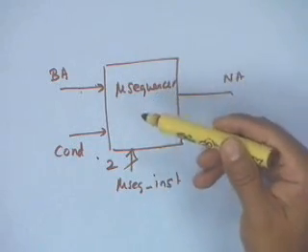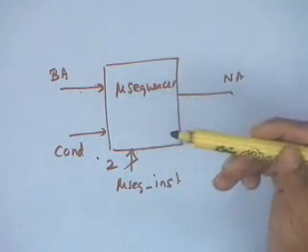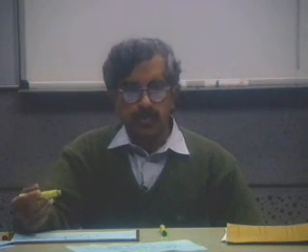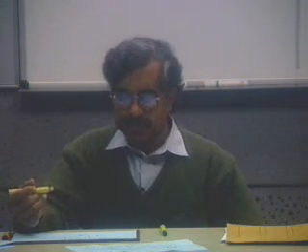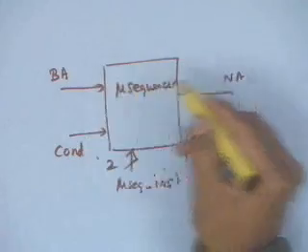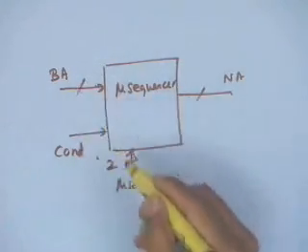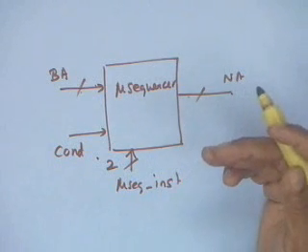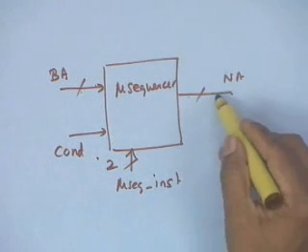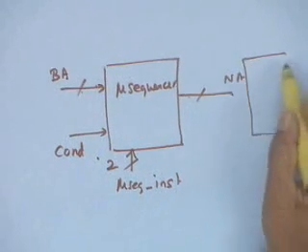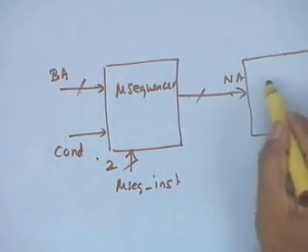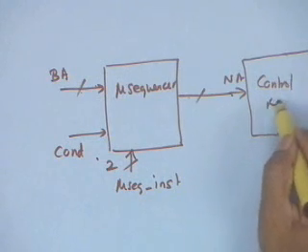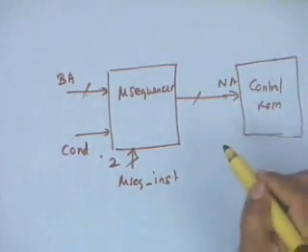The way the microsequencer is designed is you can talk in terms of customizing a generic microsequencer. Basically, there are only a few options, and from those options you can choose and you can also size them depending upon your requirement. There is a requirement for sizing this, and these 2 are equal typically. This will come from the size of your microprogram because this is being fed to the control ROM. This is being fed to the control ROM as an address. So this depends upon the size.